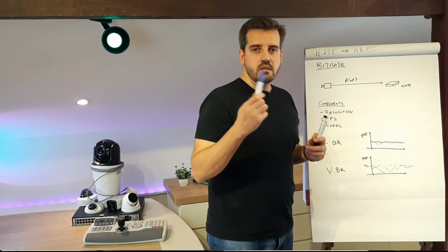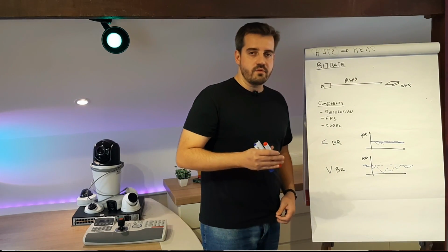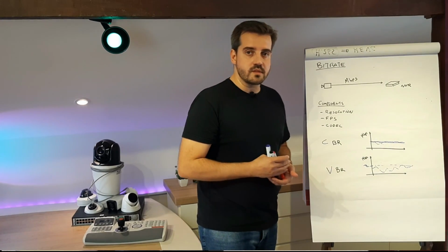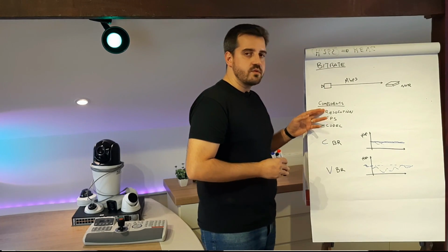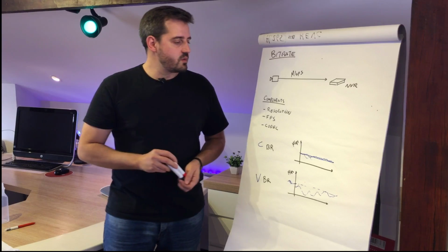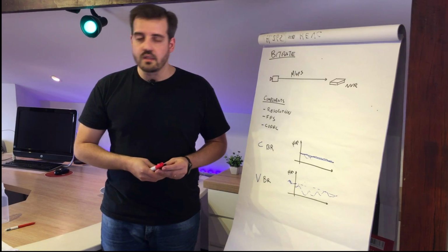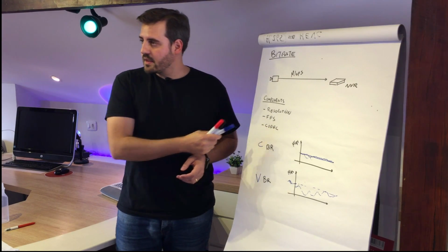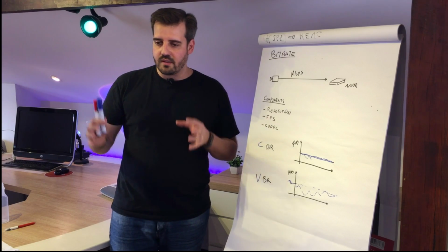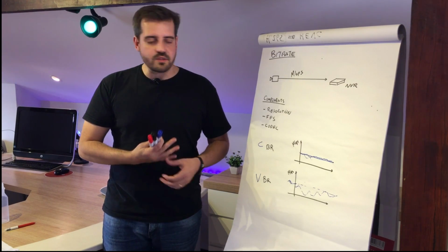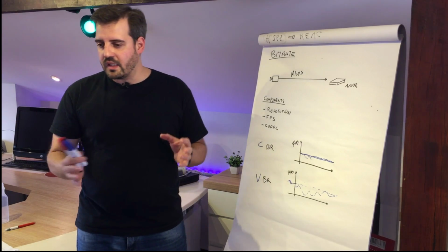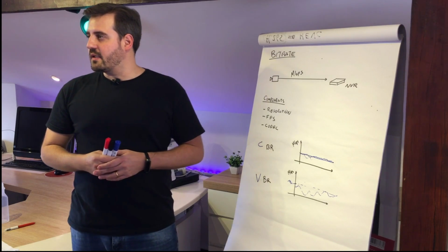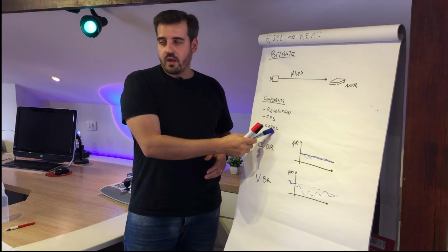So in summary, these are the components that we have in the video stream, and knowing them better now, you'll be able to understand what kind of resolution you really need in your project, to not put everything in high resolution, and to really understand for each scene whether you need that resolution. FPS, same. Do you really need a fluid view of movements in your scene, or can you have it in a slightly robotic mode, which will save a lot of space and bitrate? The codec used matters as well, depending on the camera.